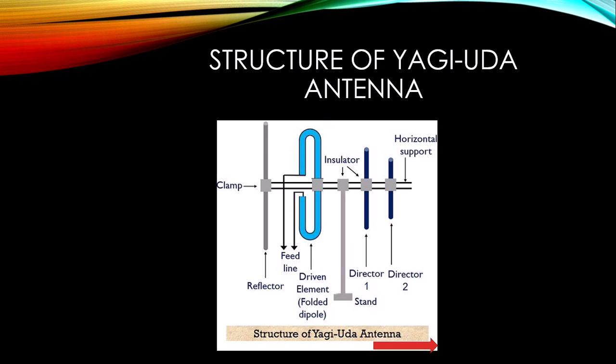Basically, the arrangement is said to be an array of active and parasitic elements. The dipole, generally a metallic rod, acts as the active element, and external feeding is provided to it using transmission lines. The reflector and directors are the parasitic elements of the structure. The parasitic elements are also metallic rods placed parallel, in the line of sight orientation, with respect to the driven element.